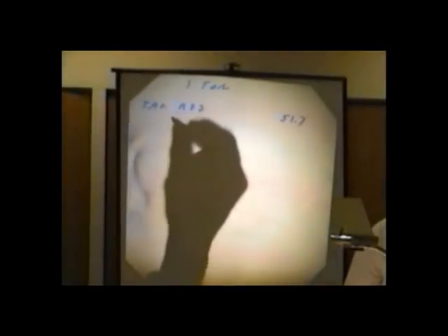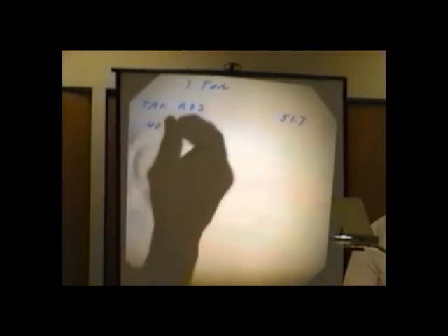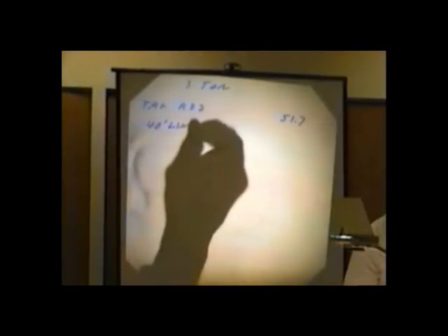Yeah, right. Let's just say, as an example, we have a 3-ton system. And on the tag, it says R22, and it says 51.7 ounces. Now, as an example, I'm only giving you an example, let's just say we're putting in a 40-foot line, and we're doing it 3/8. So now we're one size above the standard liquid line size. Okay, so it should be 5/16, but we're going above to the 3/8.